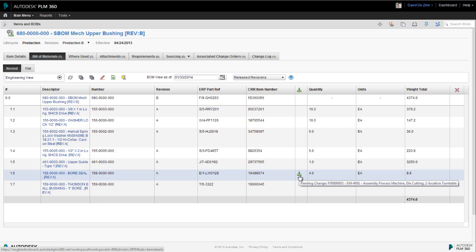So having this fact plainly highlighted to us means we can take this into account in any decisions we make. If the manufacturing team were about to build an assembly, for example, seeing this on the bill of materials may prompt them to ask questions rather than blindly building a product with obsolete or faulty parts. This reduces the risk of potentially costly and time-consuming downstream errors.